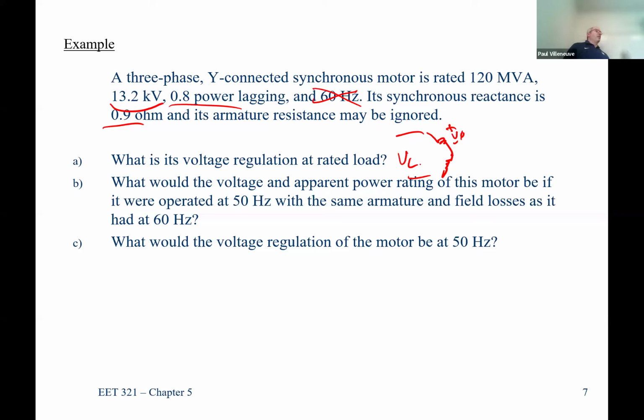The only time you don't see it is when it's really obvious. Like if I told you I'm in a 3-phase industrial facility and I said, hey, that's a 120 volt system, you almost guarantee, no, that's a phase voltage, not a line voltage. Because that's one of those ones where we just use 120, and that's only because that's what we use here. If you were told 120, you almost guaranteed know that system is rated at 208 volts.